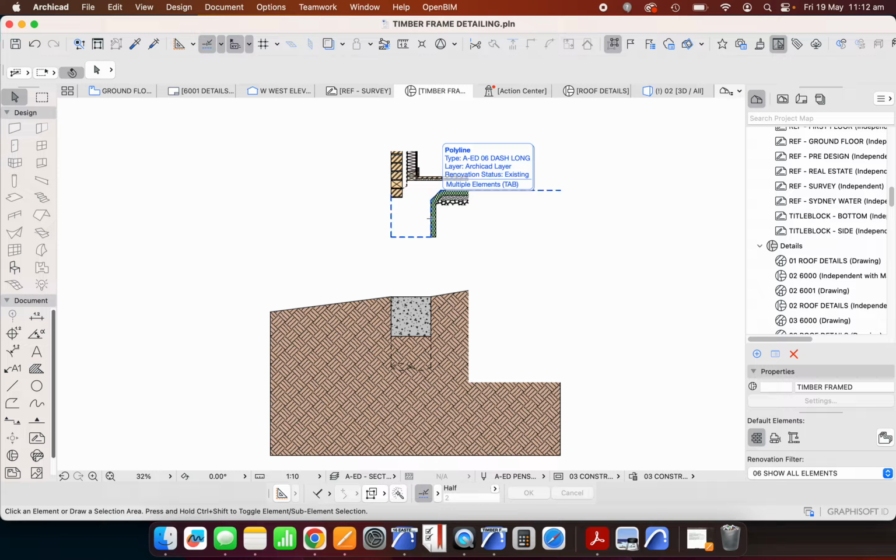is I could select all of these, and I could do this in one go to make life a bit simpler. So find and select, pick up the setting of that fill, add. I need to find some other way of differentiating between these elements. So I'm going to use fill, add. It's going to find my fill type, and then I can select all of those bricks and change that to a darker orange. The reason why I want to do that is because I want to show that these are in section and this brick is in elevation.